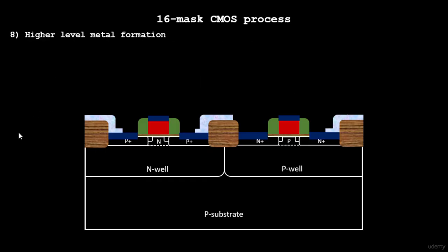In this case the boron does the same thing. It enters this particular open area. So this is the open area for boron. It will go here and settle down in this area. And this is now the P plus implant. So this is a similar structure to what we needed for your PMOS. We wanted a P plus, P minus, and an N kind of structure in this case. Okay, so this is your PMOS, this is your NMOS.